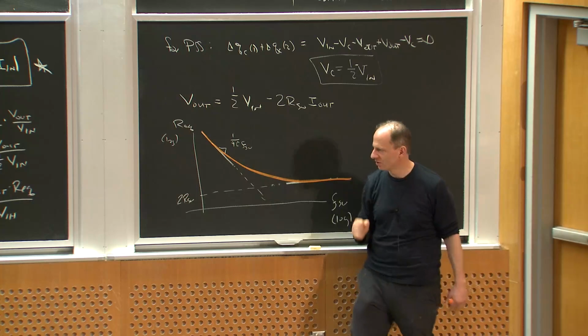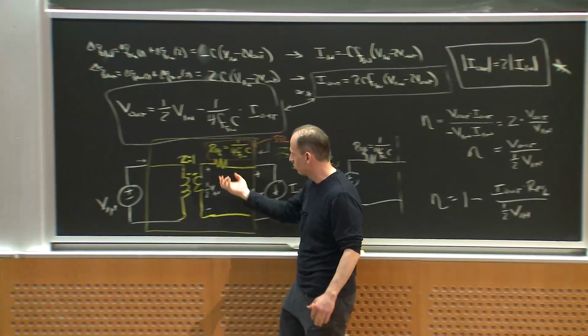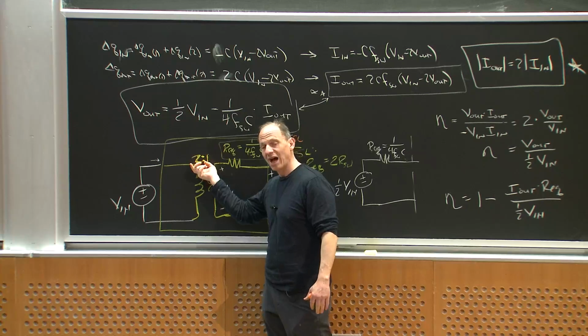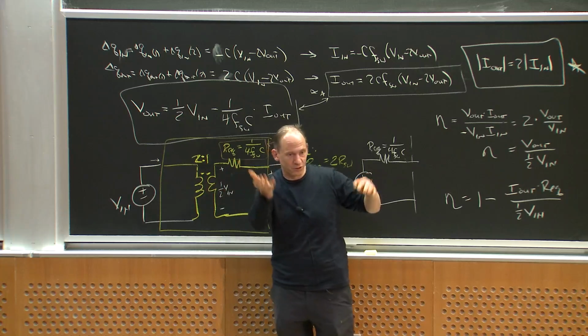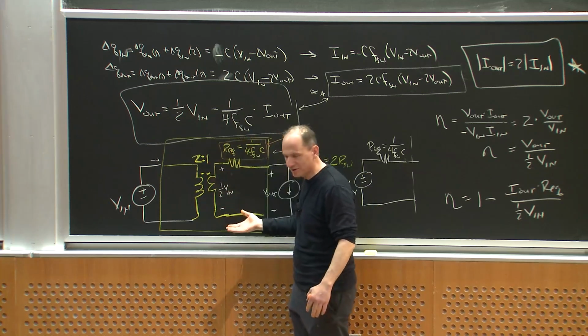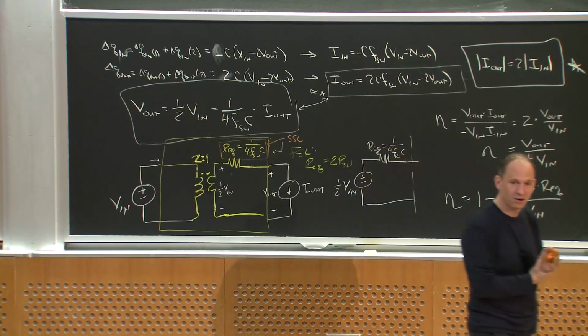And the result of this is, if what I want is a fixed conversion ratio close to this, I can get extraordinarily high efficiencies and power densities. If I deviate the voltage conversion ratio away from that, then the efficiencies start to droop. But for what they're good at, switched capacitor converters are very hard to beat.